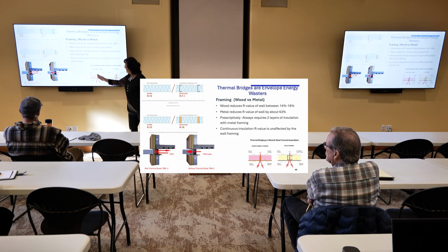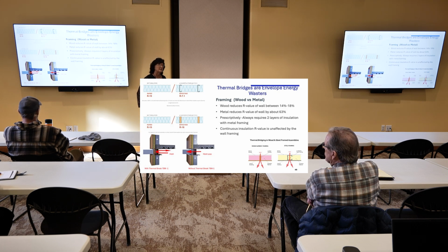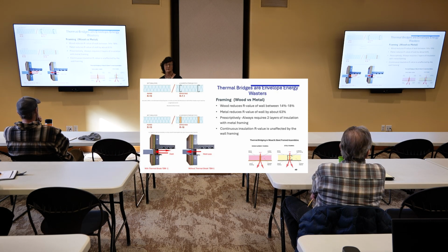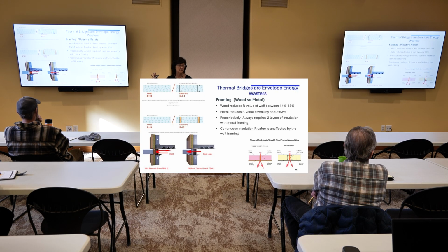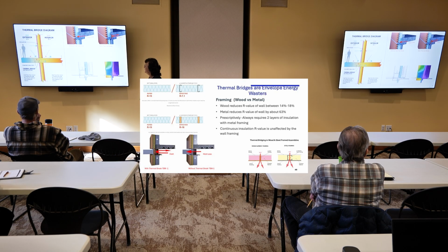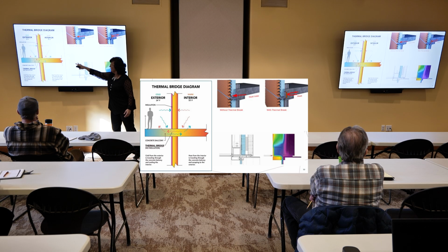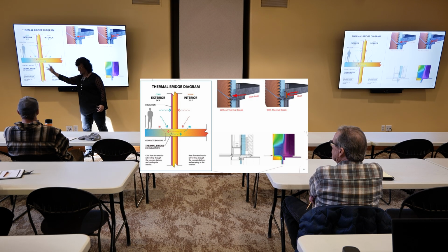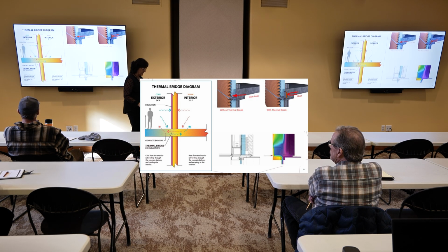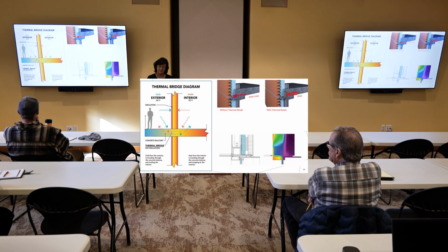Yes, wherever you have a stud, you're going to have heat loss, but there's other places where we're going to have even more heat loss. I have some jurisdictions that require that you can't trade out of continuous insulation for the thermal bridging aspects of it. There's all kinds of ways. We see floors or slabs that run continuously in and out of the building. It's taking that heat with it. And so what do we do there? There's all kinds of places that we have thermal bridging.